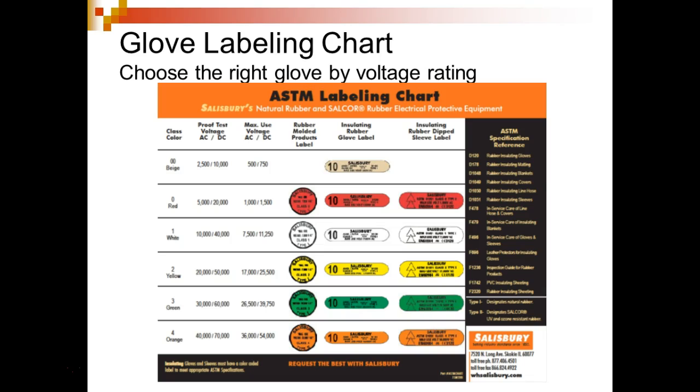So we're in 0. That was well below 0. And the only thing we're supposed to be able to wear is rubber gloves. And they should have what color? Can you see that color? Beige, yeah. And this would be the colors for class. We're in 00, by the way. Class red, class white, yellow, green, and then orange means that's the bad stuff, right? We're okay?